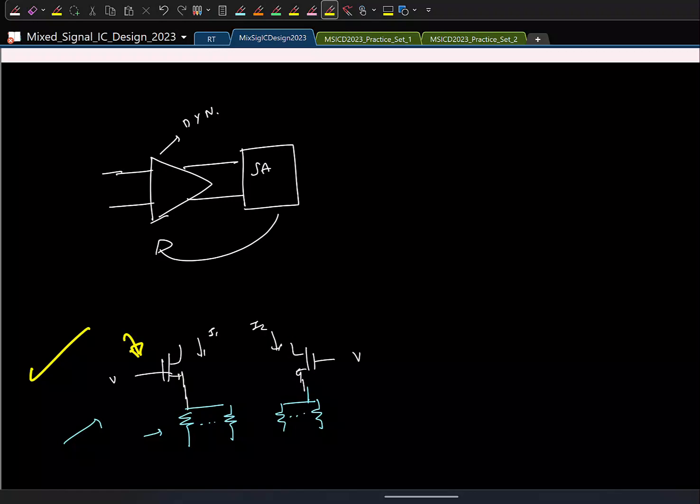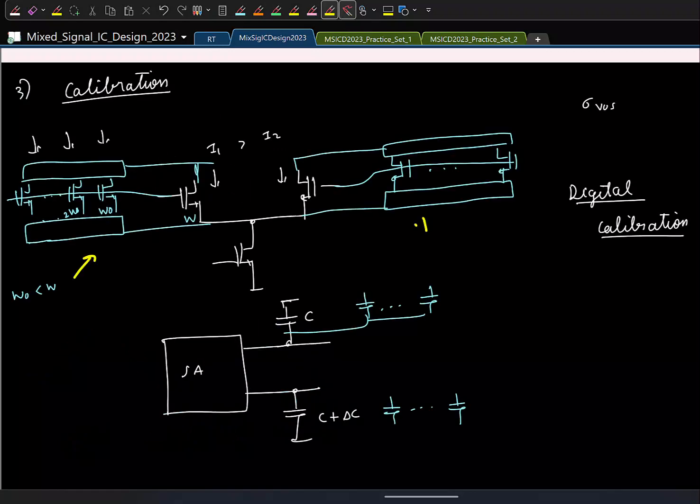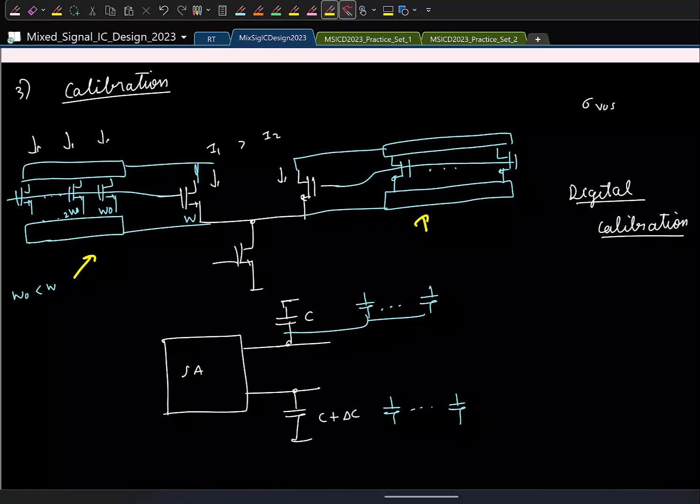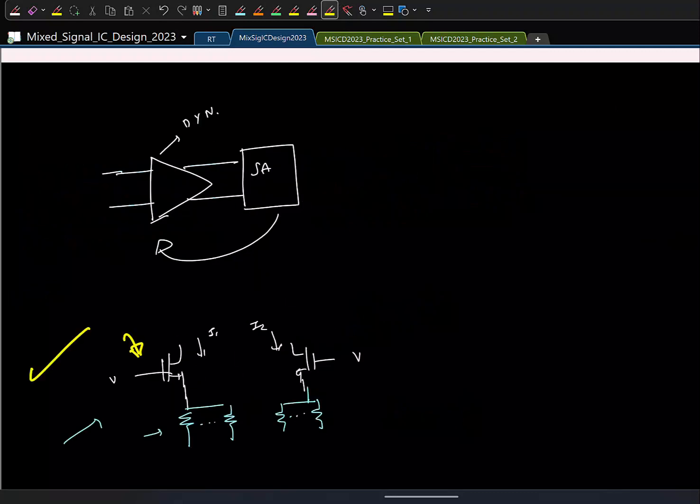Because as he mentioned, if you put different transistors in parallel, now on one side the number of transistors might be larger than the other, which means the gate capacitance on one side is larger than the other. That will present asymmetric load to the previous stage, right? So the common way to tackle it is using this thing.